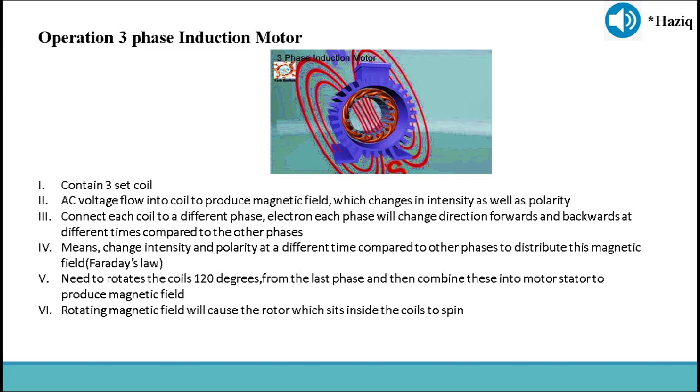When the rotor is standing still, the flux of the rotating magnetic field cuts every solid conductor of the rotor. As the rotor conductors are stationary and the sinusoidal stator field is rotating, there will be a change in flux linkage with the rotor conductors. As a result, there will be an induced current in the rotor conductors as per Faraday's law of electromagnetic induction.